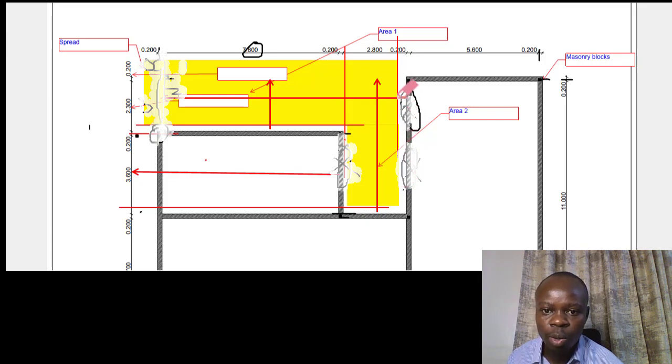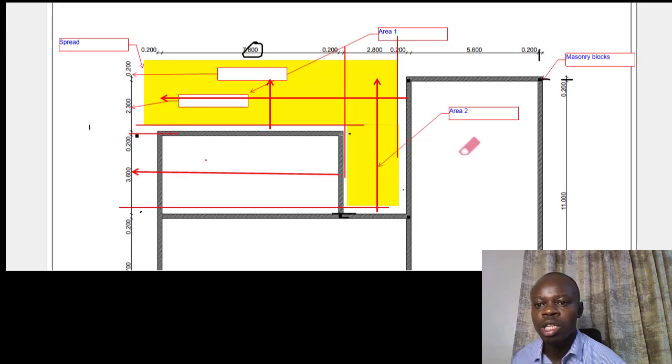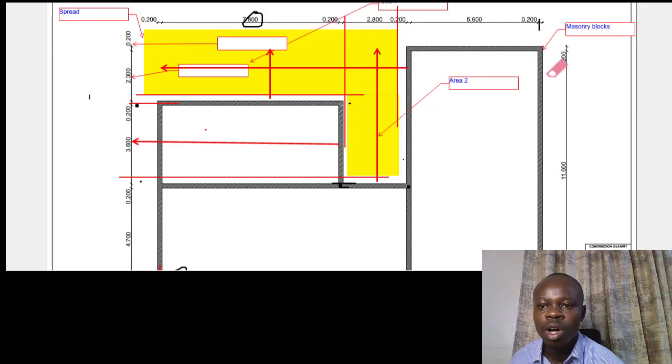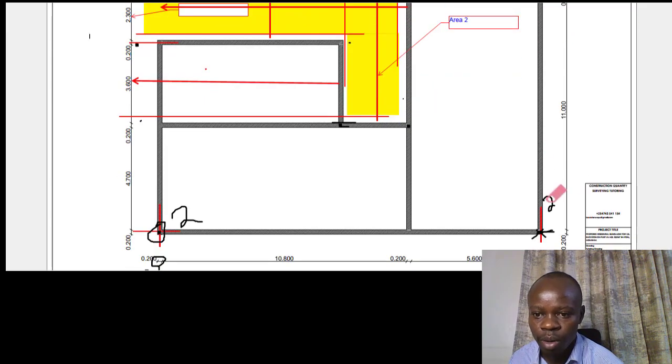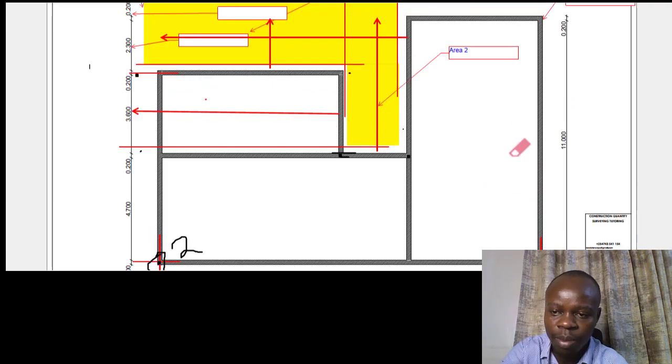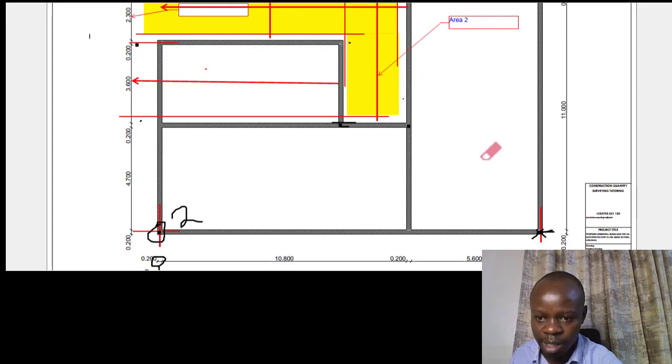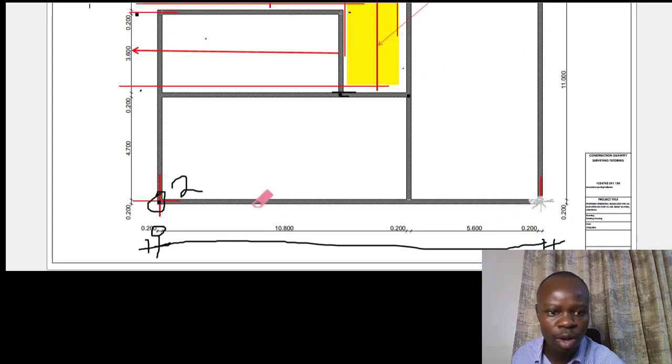So when you use the rule of distance moved, you can have your dimensions from the external faces of the external walls, all of them, including the recesses. So you simply calculate the perimeter of a perfect rectangle by having your dimensions from the external faces. Just calculate them the way you will calculate the perimeter of a rectangle.